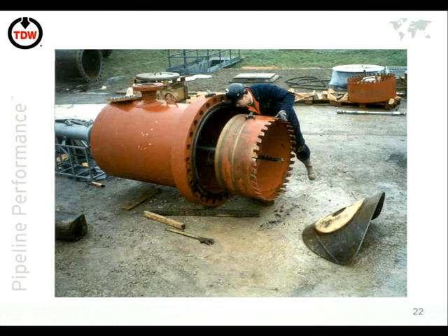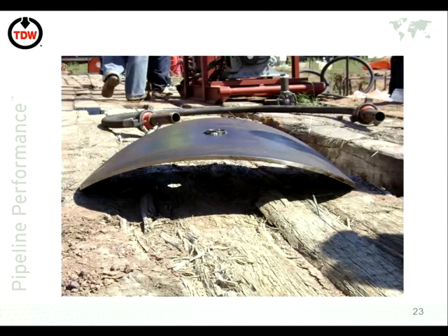Again, this is just some examples of the coupon which is coming out. You can actually see the profile of the pipe itself, so that obviously the actual pipeline is something like that. Excuse me, how to avoid spark when you are cutting it? I'll come on to that because everything is self-contained and it's purged before you do it. So if you think of the early slide of the drill, it's not like that. Everything is contained in a pressure containing system which will be purged with nitrogen. So even if a spark did occur, there's no oxygen in there. Because the only thing you have is nitrogen and the product itself.